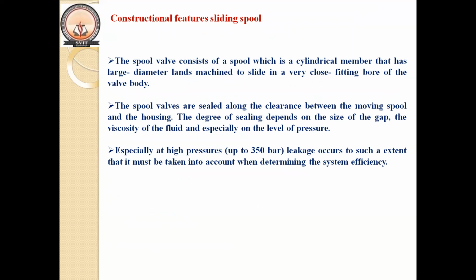Especially at higher pressure, that is up to 350 bar, leakage occurs to such an extent that it must be taken into account when determining the system efficiency. That is, the amount of leakage is more, especially at higher pressure operating conditions.